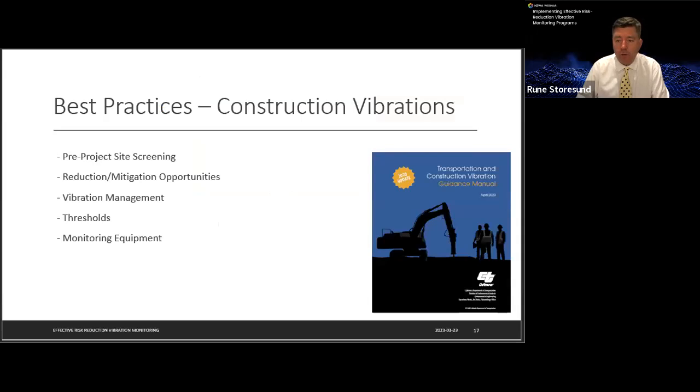So in my view, there are 5 primary components you'll want to be aware of when it comes to best practices associated with construction-induced ground vibrations. First, you want to do some pre-project site screening to ascertain your potential exposure to construction-induced ground vibrations. Second, depending on your exposure, are there mitigation opportunities for you to reduce or even eliminate substantial ground vibrations?